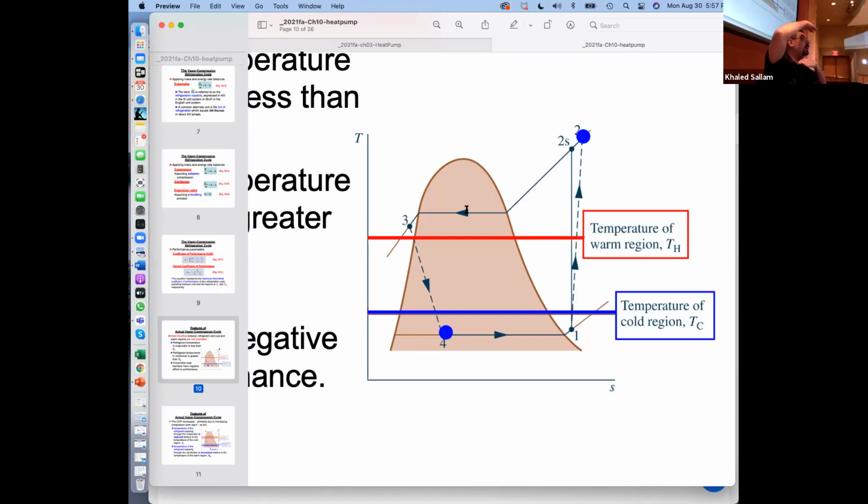But the bigger the delta T between the refrigerant and the ambient that you are transferring to, the smaller the size. But you have to spend a lot of energy to go that high. So again, it's the compromise between: do I want to build a smaller heat exchanger because I don't have the space? It's a tight unit, but then I pay every single day in electricity. Or do I want to build as big a surface as possible, and therefore I can have a very small delta T between them, so my compressor does not have to work as hard.